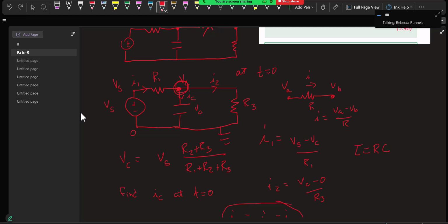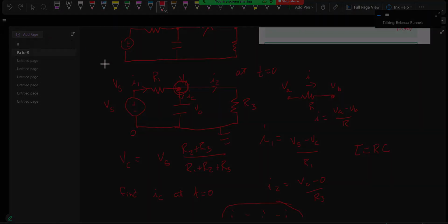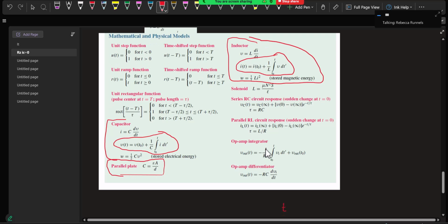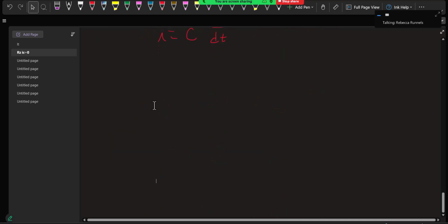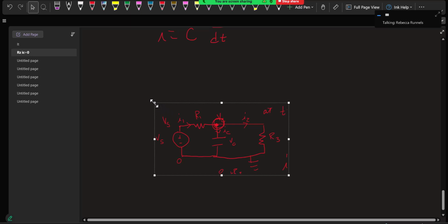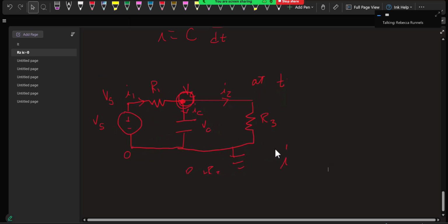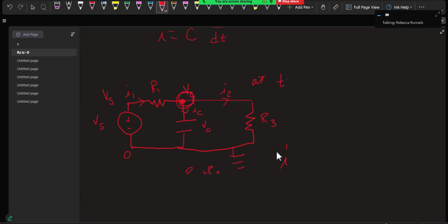So what does that R refer to? Our R equivalent. So what would R equivalent be on this one? I didn't mean to be doing this problem because we're starting with the hard one. So which R are we talking about? Both, but through where the capacitor was. What you have to do is look at it from the point of view of the capacitor, and you ignore sources.